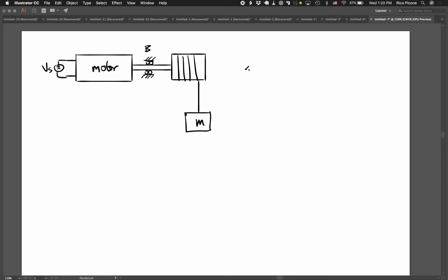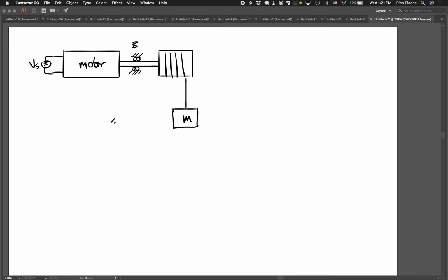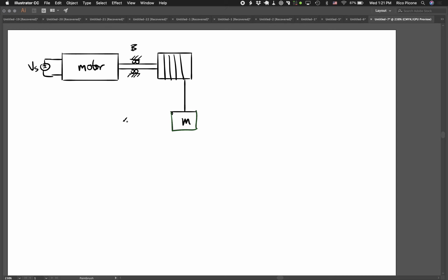In a lot of cases, you're going to have a gearbox on this motor so that you can change the torque speed characteristics, run it more efficiently, that type of thing, or get more torque out of it. But we'll ignore that for now. Maybe later we'll do one where we also have a gearbox in there. Gearboxes are something we can handle now because we have transducers, but in this one problem I thought maybe it would be good to just do this. This is the one we looked at before, but remember we modeled the motor as a torque source, and then we had this weird torque source relationship here on the motor.